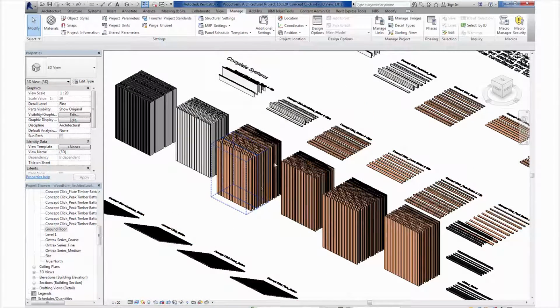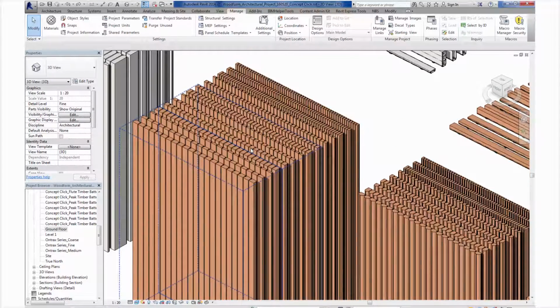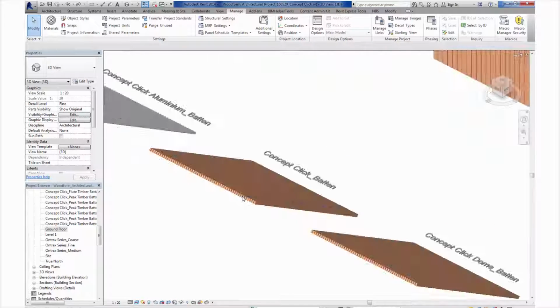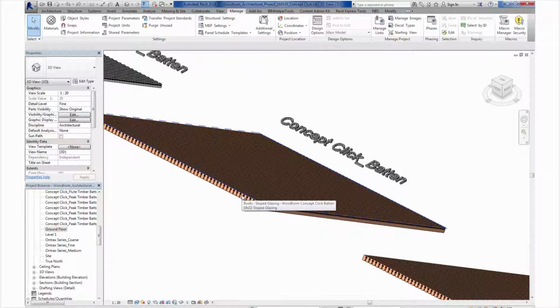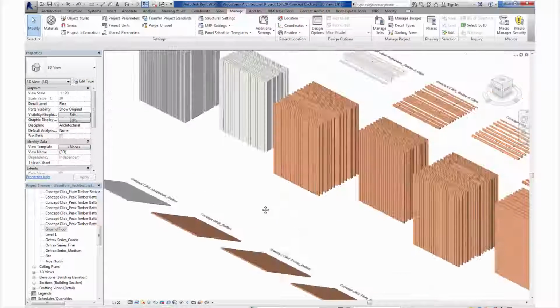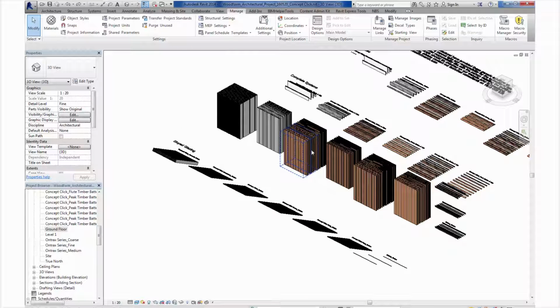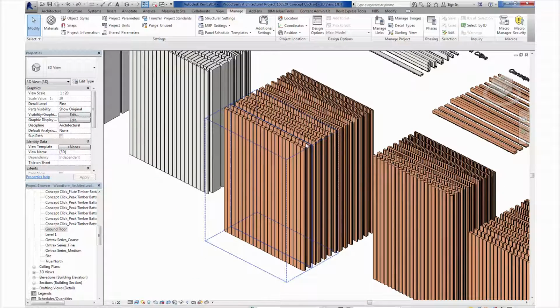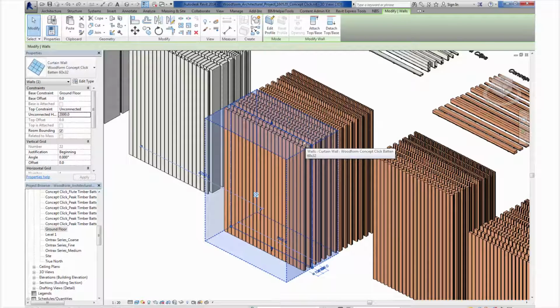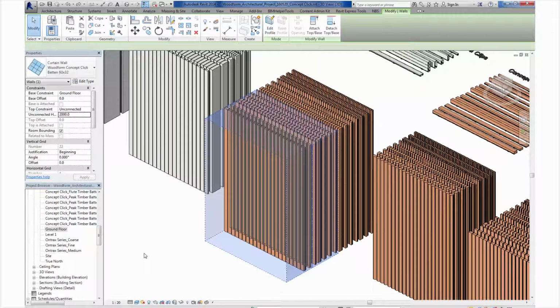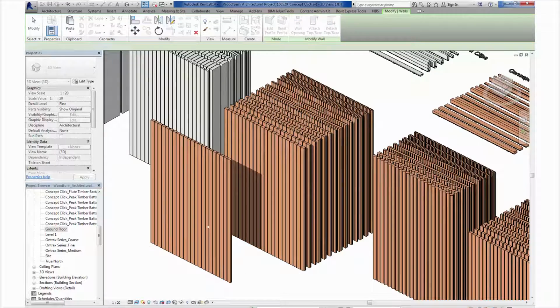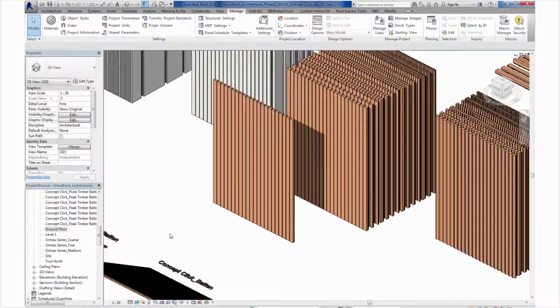The curtain wall families, just like the loadable families, have been pre-configured with all the different profiles. The slope glazing, on the other hand, has got one typical profile, but each batten can be swapped out to create all the different ranges. The reason why we haven't included all of them is a simple case of file size, because there is a couple of hundred of families in here, and you'll note that the file size of the project is already getting quite up there. But the process in order to get this into my project is simply a case of copy and paste the family. I'll just do it in the same project to give you an idea, or the usual transfer project standards function.